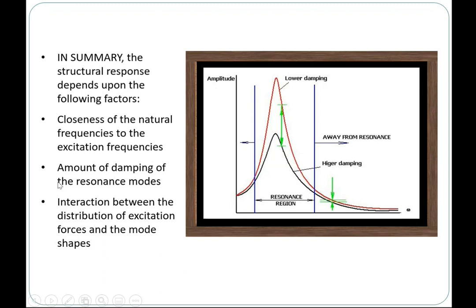And if you have the natural frequencies with the damping, then you know that at a certain natural frequency, even if your excitation frequency coincides with it, you will have low vibration because you have high damping. Together with the mode shape information, you will know that if a force is acting on the nodal point of that particular mode, even at the excitation frequency, it won't cause any high vibration issues. So these three factors help us to explain.